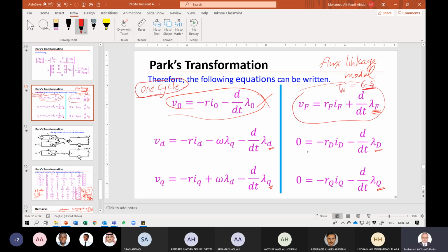So the field winding or exciter circuit will not change the field winding voltage in this very short time, in milliseconds, 16 milliseconds or so. So if you want to study the stability of the system within this frame, as we did before, we have only the swing equation. Second order model is enough.